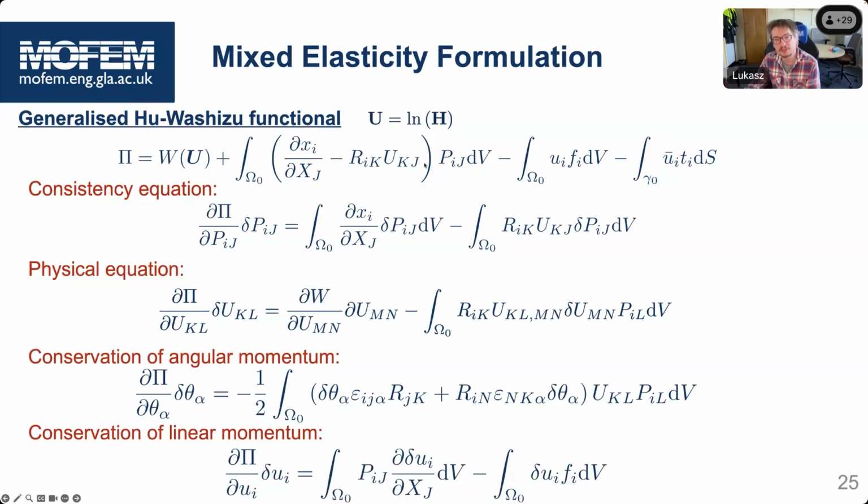In other words, we want to satisfy the continuity of the fluxes a priori. And so traction boundary conditions become essential boundary conditions, and we have continuity of fluxes enforced a priori. We enforce the continuity a posteriori once we solve the system, and displacement boundary conditions become natural boundary conditions in this formulation.